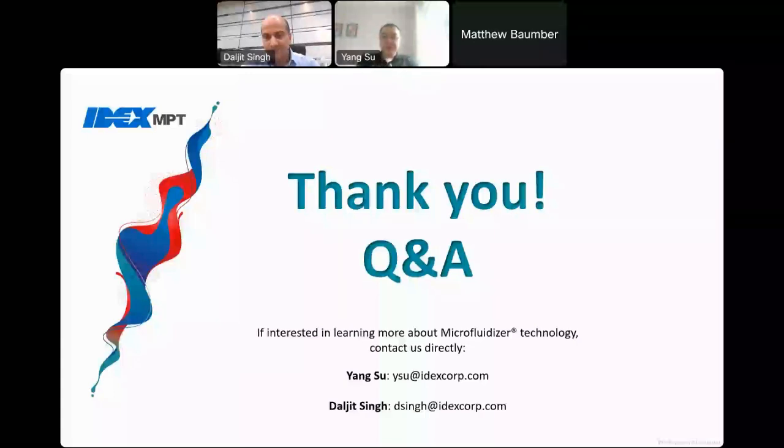Right, great question. We do a lot of work in our design process to design our multiple channel chambers. The one thing we need to make sure of, like I mentioned in the presentation, is that you need to be able to maintain the pressure. When we use a multi-slotted chamber for a larger scale machine, we will carefully choose the number of channels so the machine can still achieve the desired process pressure.